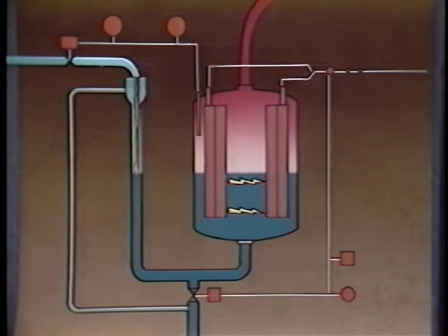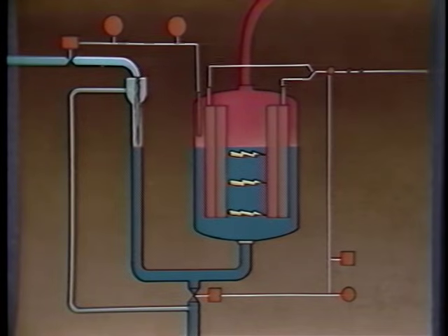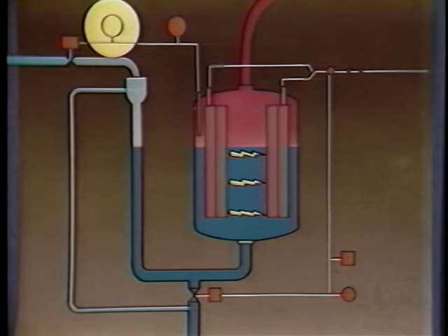When the water contacts the electrodes, current flow starts and is sensed by the controller. The fill valve is held open until the current flow in the tank reaches the level necessary to produce enough steam to satisfy the humidification requirements at the humidistat.